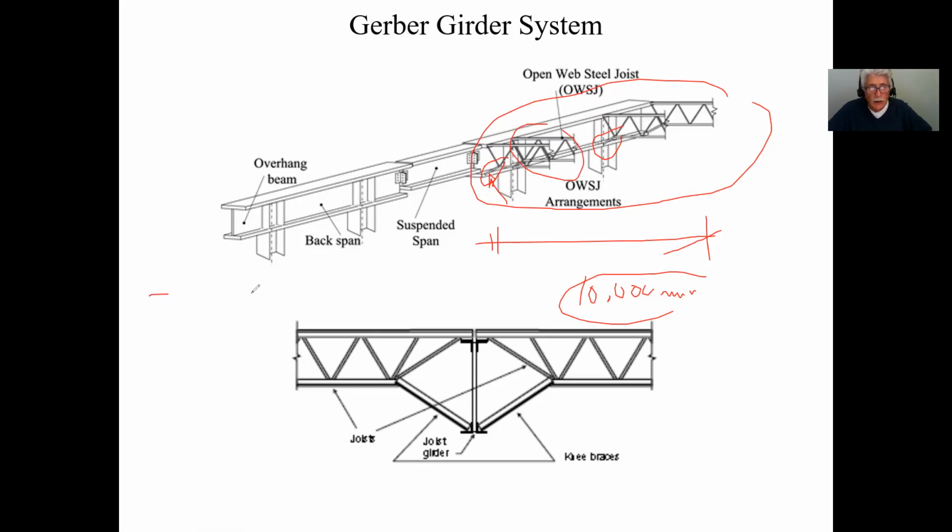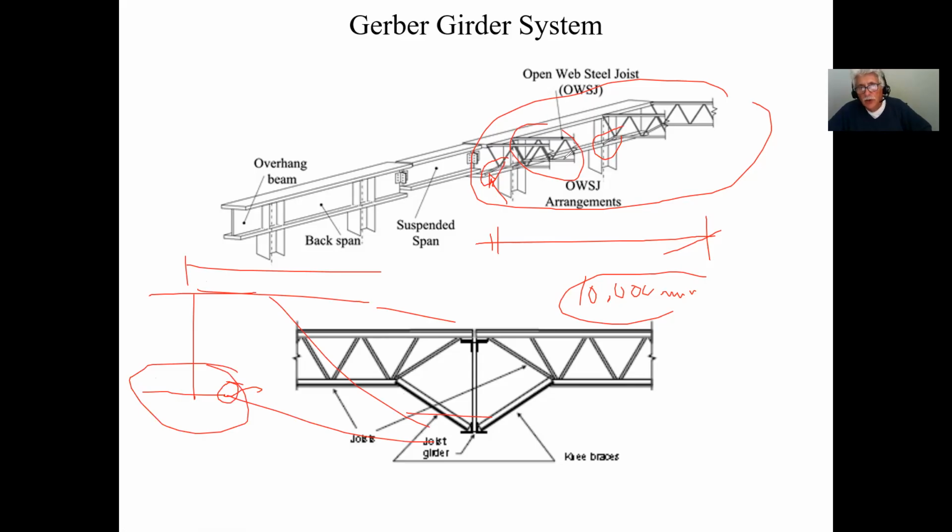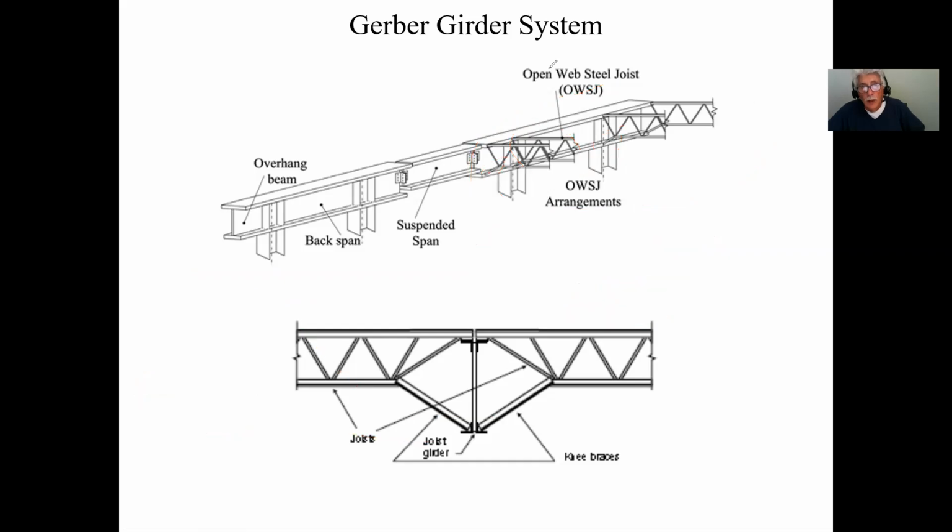So what's gonna happen is that this is going to be our girder here, okay? Our joists are gonna be sitting on top here, like this, right? And then we'll be putting a knee brace so that we can laterally support the element that's in compression here, okay? And that's how you can reduce the LU. So I hope I didn't go over everybody's head, but in other words, as long as I'm holding the compression element of my beam, that I reduce the LU. If I don't hold that compression part of my beam, the LU becomes the whole beam, okay? In this case here. So we're gonna do that, or we're gonna see if we need to do that.